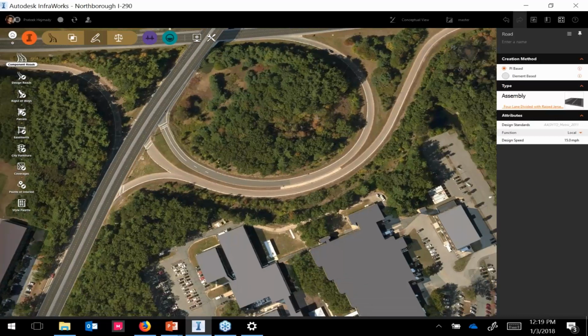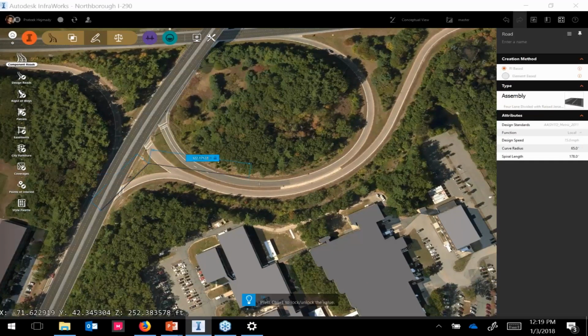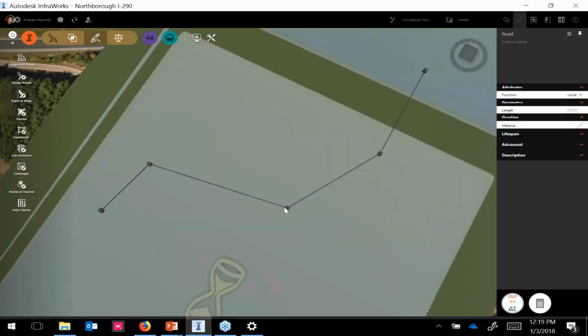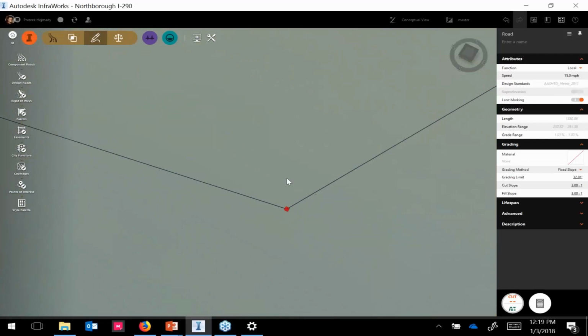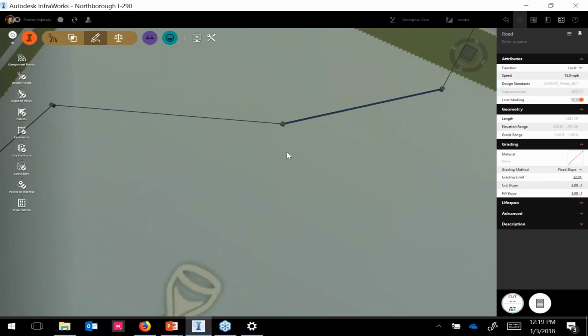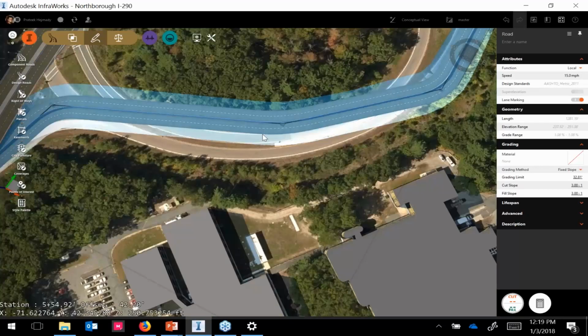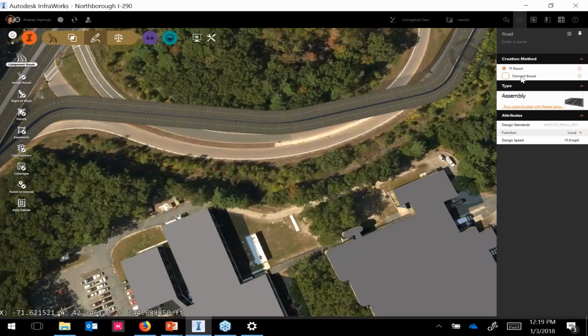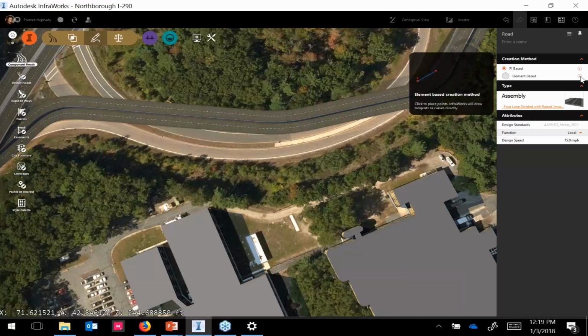So today how it works is you would create this sort of PI-based layout. And a lot of the times what would happen is we would not get the flexibility that was desired when creating this PI point. So a new way of doing this, just going to wait for a sec for the model to refresh, is what we've introduced as a tool called element-based layout. Now the difference here between PI-based, which is like I said, you create a point of intersection and the curve gets added in, the element-based lets you have the control over creating the geometry by hand.